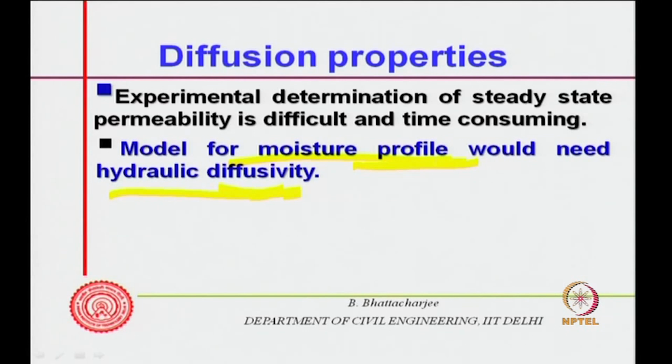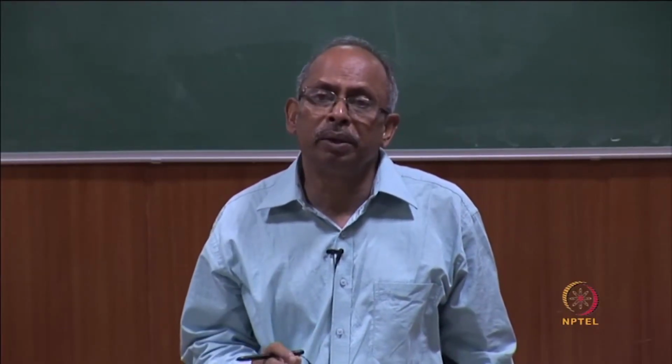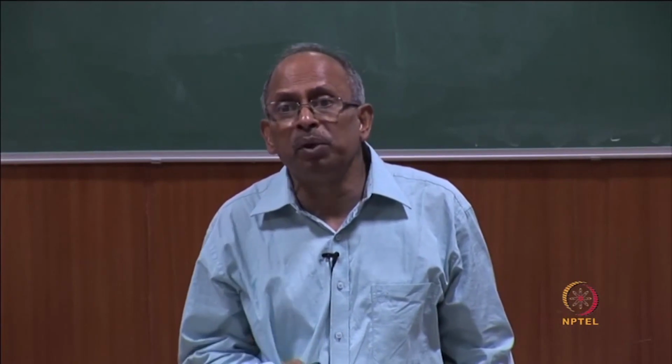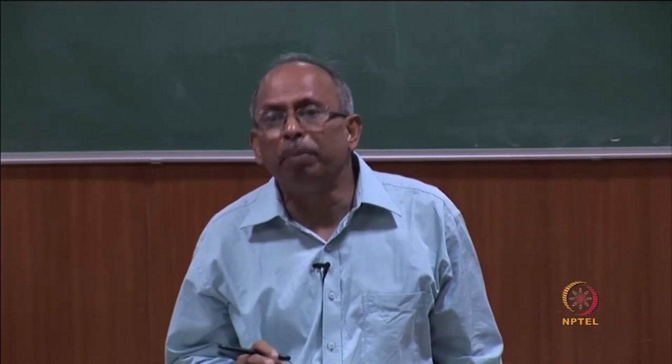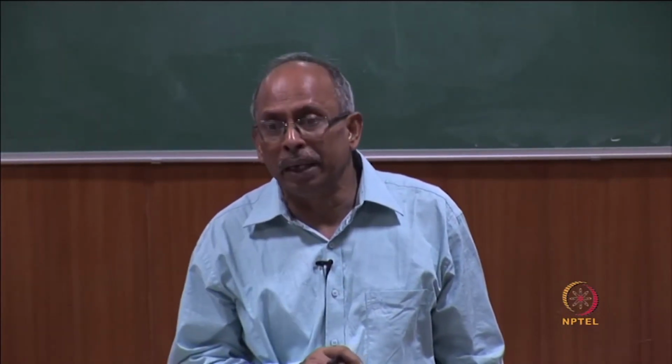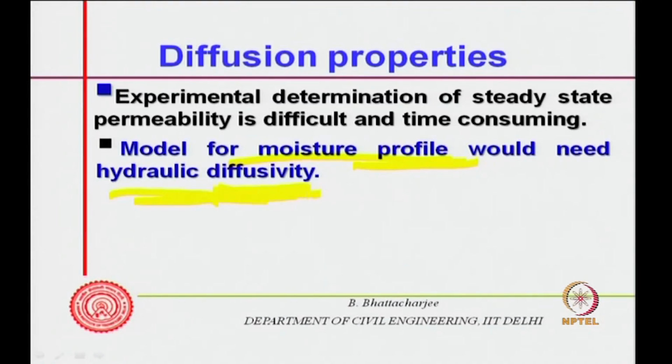So, diffusion properties are diffusivity, although they are not necessarily diffusion as we understood from Fick's law, that is concentration dependent diffusion. The diffusion of oxygen and carbon dioxide will be concentration dependent, a function of the concentration gradient. But water diffusion, or hydraulic diffusivity, is not exactly diffusion; it flows under capillary suction or under vapor pressure gradient. So, for the water situation, hydraulic diffusivity one can use,